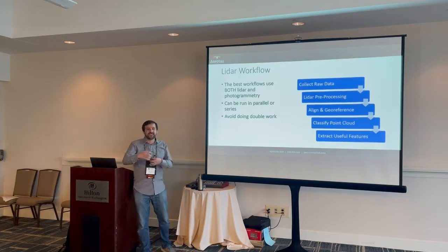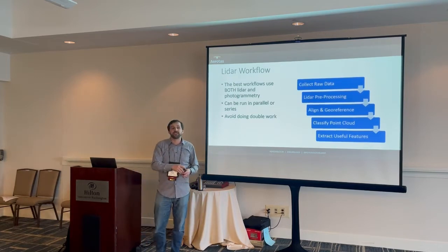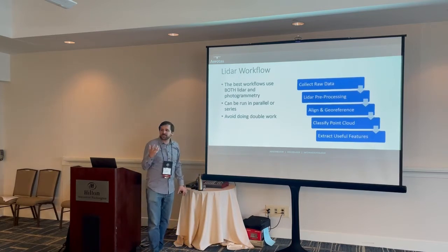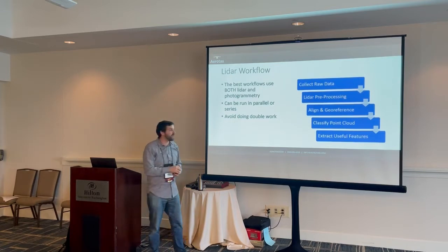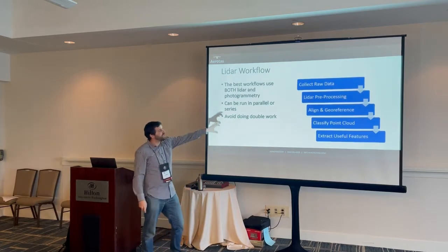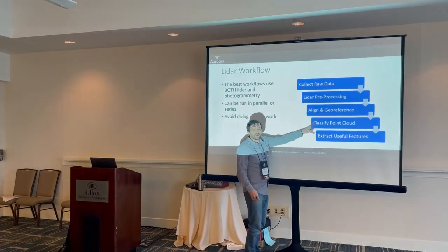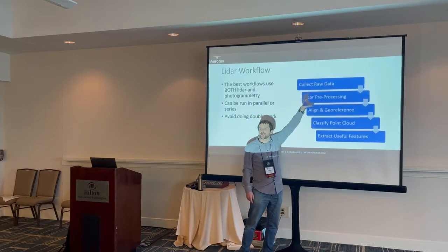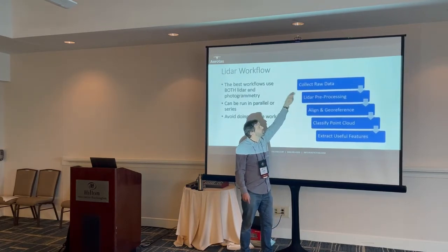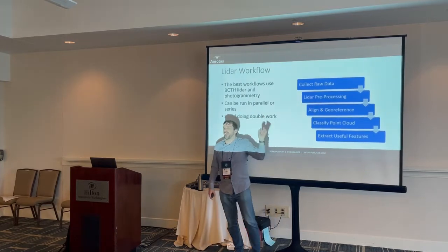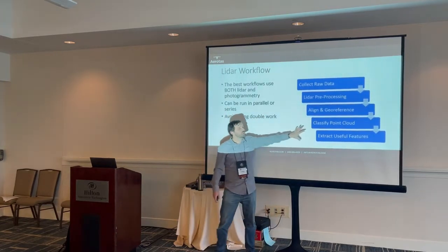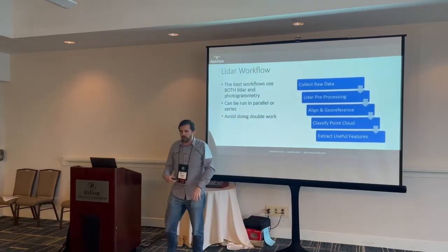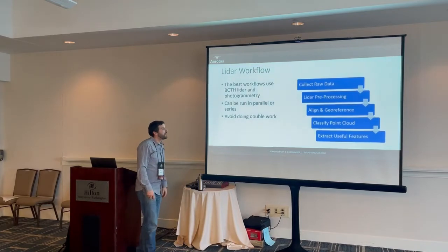So modeling that, getting it into something useful that you can actually send to a client, that's where extracting those useful features comes in. And all of this is happening before CAD. There are different ways to get all of that done, but these last two steps are the real time killers. Generally speaking, these first steps are what get you your accuracy, right? Collecting the raw data, pre-processing it, and aligning it, that's how you get an accurate point cloud. And these two steps are how you get something useful out of it. That's really the Lidar office workflow processing in a nutshell.